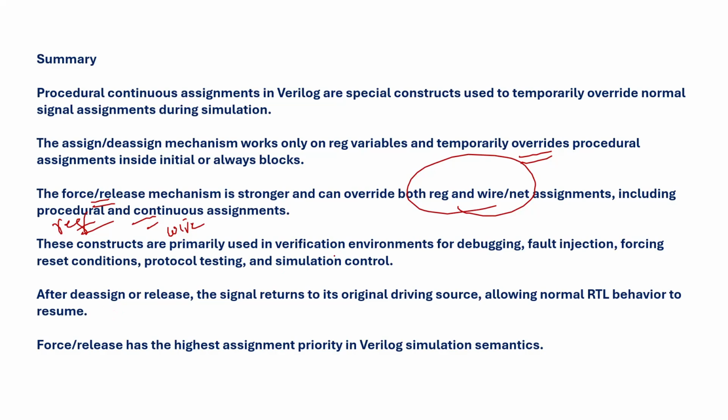And where do we utilize this? Debugging time, some fault injections at this time, some reset and force. I want to reset my configuration; at that time I utilize force. And with assign and deassign, after deassign or release the signals return to the original driving source. Whatever the original values you had, it moves back to those.